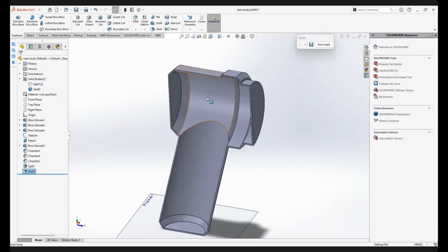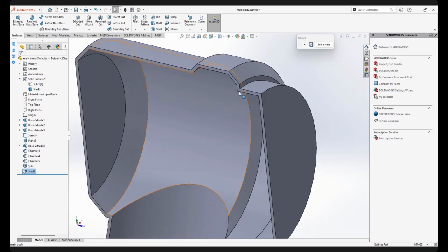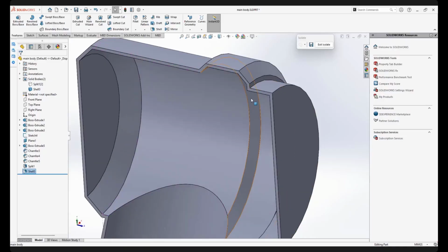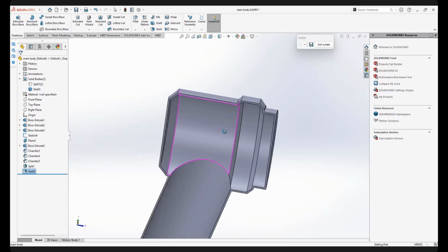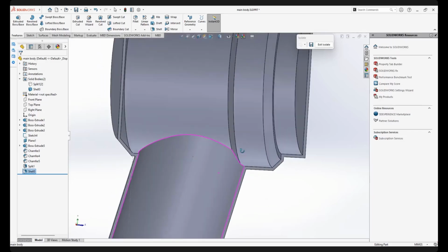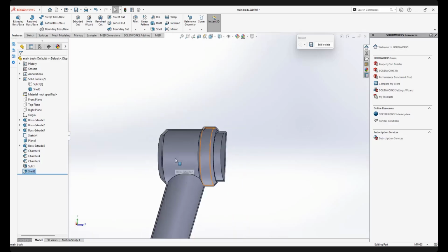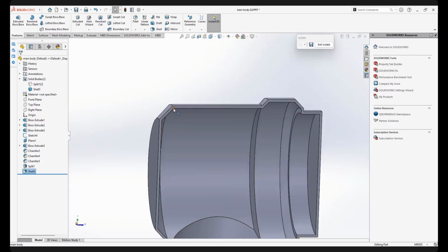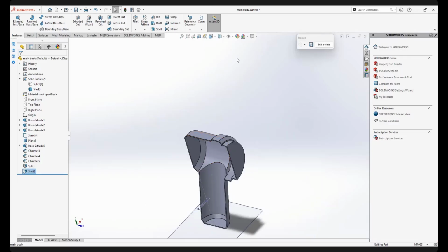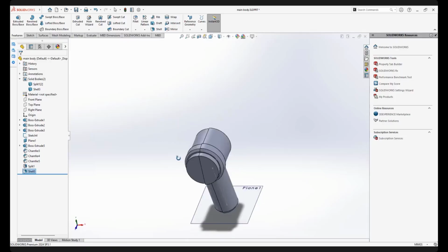Why can we not go sharp inward? I will explain to you why. Because when you have a sharp curve, logically you cannot make an internal one. It really cannot be done. Any software you use will produce an error. Outward can be done. It goes outward, right? So be careful about your dimension because you tell the shell thickness outward. So you have 1.5 millimeter. I've done 1 millimeter like that. So kind of like outward.